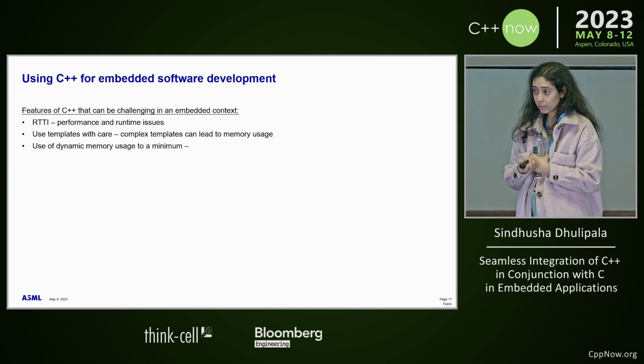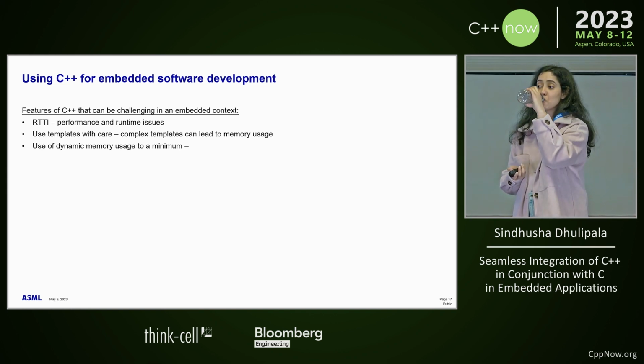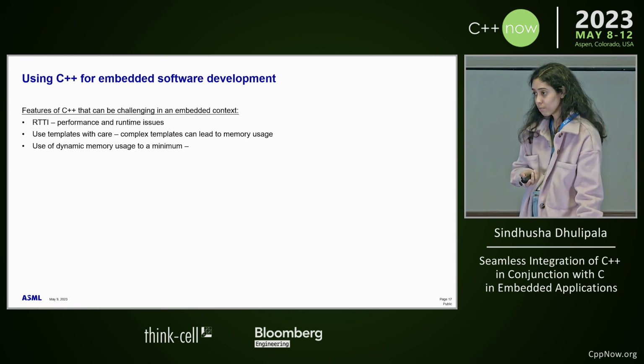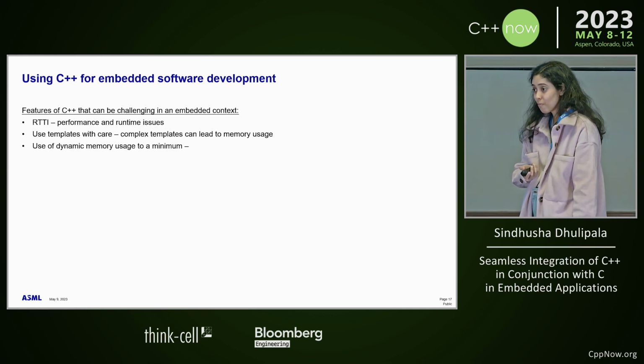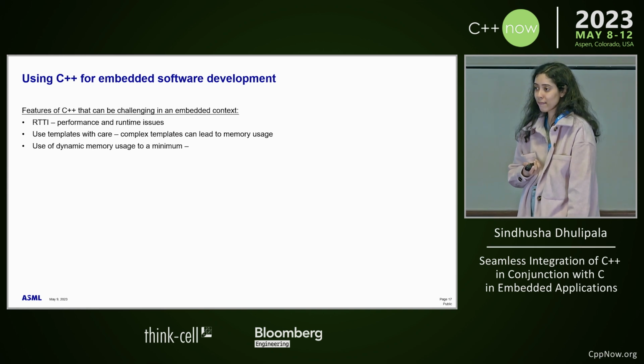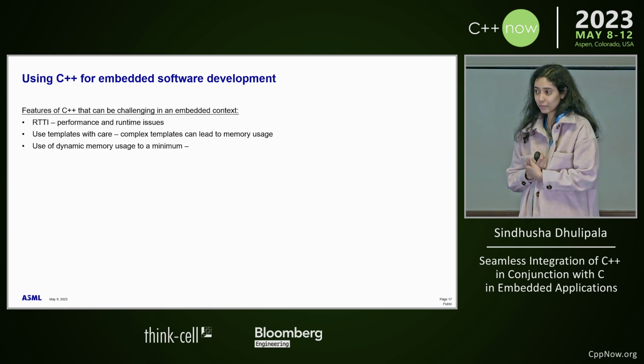I just want to make a comment. We do a lot of template metaprogramming on our firmware, and we have templates whose type name is literally kilobytes in size, and those don't use any memory at all because it's the type system that we're using. Oh, okay. And then we have other templates where we weren't very careful with the storage allocation and how they're being used, and they use many, many kilobytes when really we should have used an array or something else so that we're not duplicating the assembly code when we expand the template.